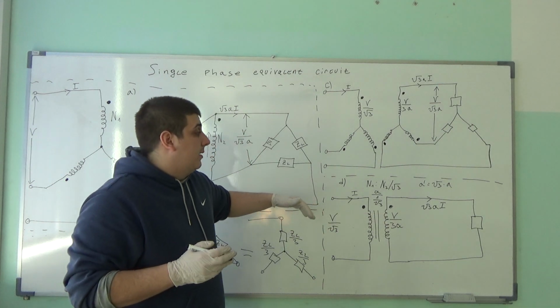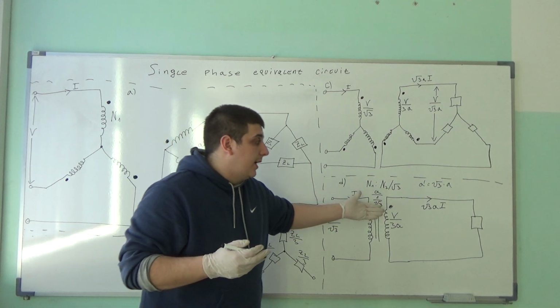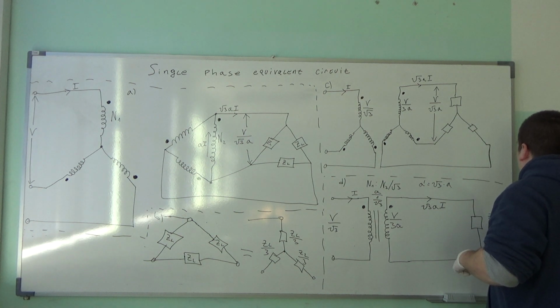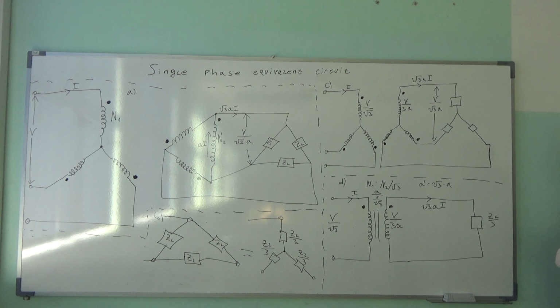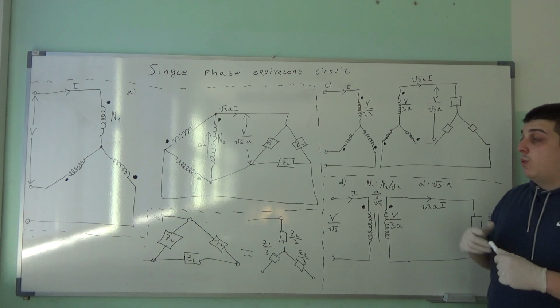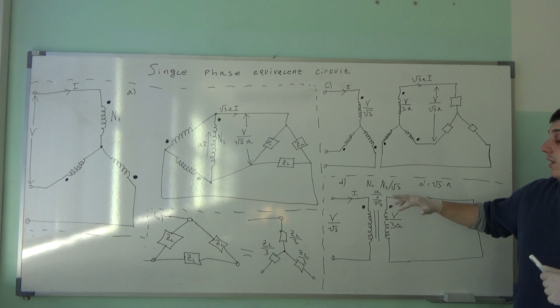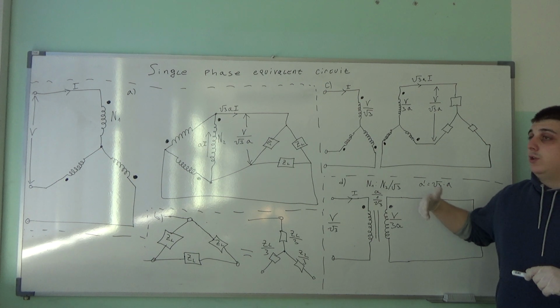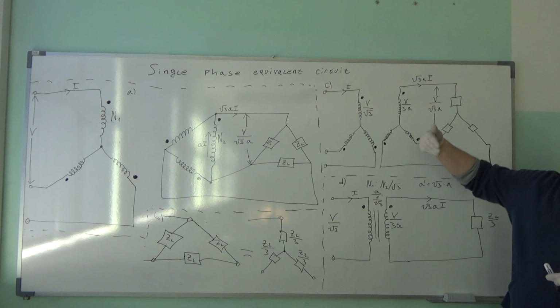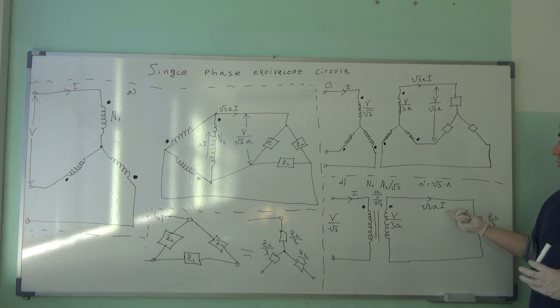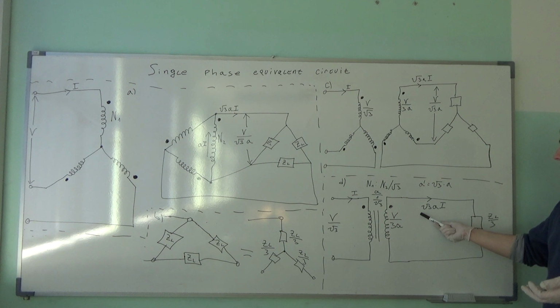Okay, and that's it. And this load is equal to Z divided by 3. Now, with this, if we know what is the load, what is the turns ratio, we can easily calculate the currents induced on the output of this transformer. For example, we can now know what is I on the secondary side, which is equal to this.